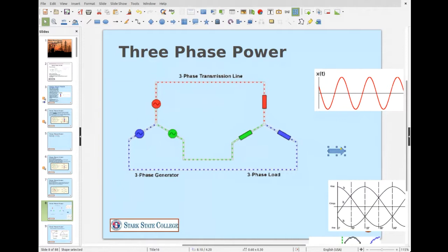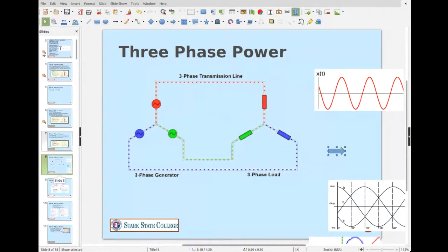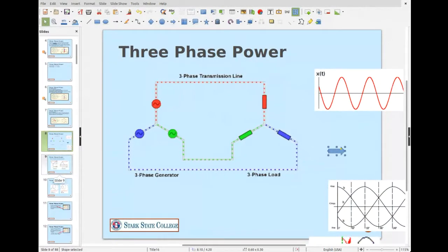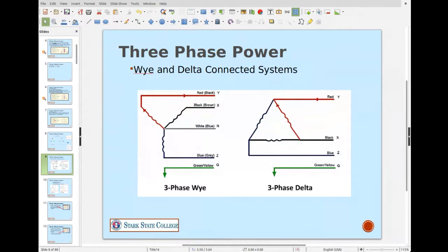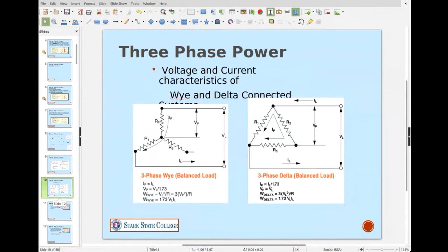Okay. And so three-phase is just very, very nice. We effectively can transmit 3 times the power. All right. So again, you can do this using a Y to delta, a delta to Y, or a Y to Y. Okay. It doesn't really matter how you're doing that, but you're going to see that now these slides are showing 1.73, which is that square root of 3. Okay. So if you remember, right, so that was the value.